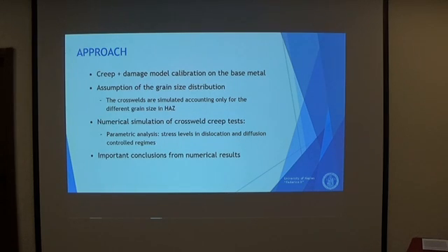To predict the onset of type 4 fracture, we just assume a grain size distribution along the weldments. So the cross welds are simulated accounting only for the different grain sizes in the heat affected zone.